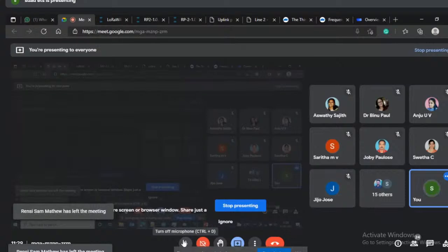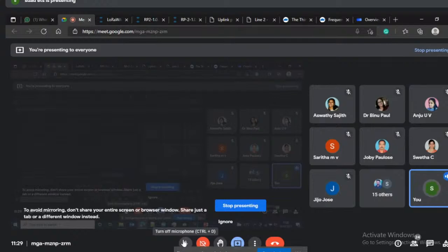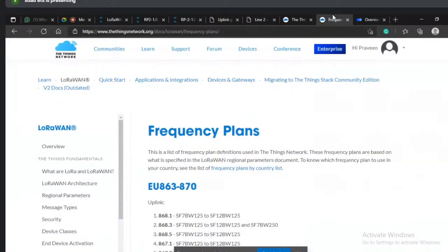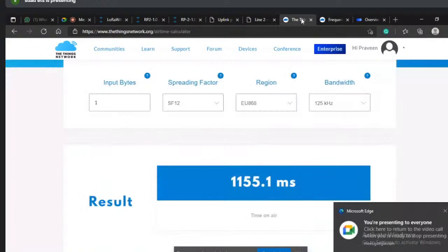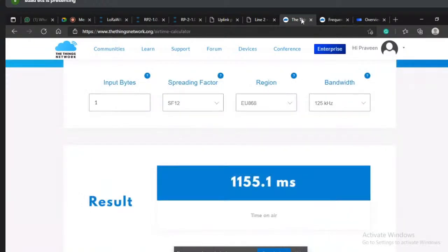Okay. So if you want to use minimum gateway power, you can use a static one, and set the spreading factor as 7. If you want to increase the coverage range, then you have to set the spreading factor higher, up to SF12. So that is the thing. Depending upon power, this spreading factor will change. That's why on the gateway side we make it by default a maximum power of 20 dBm.